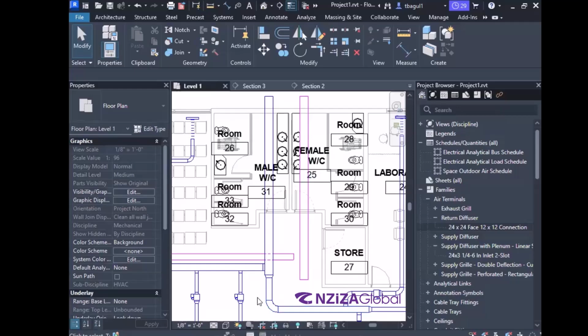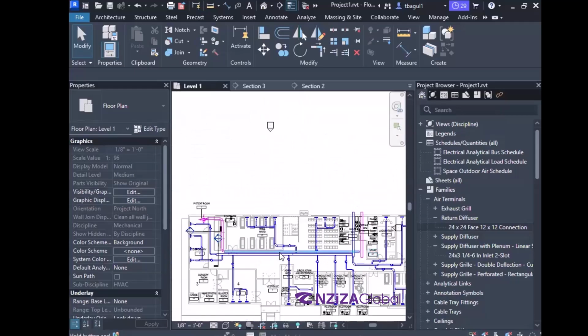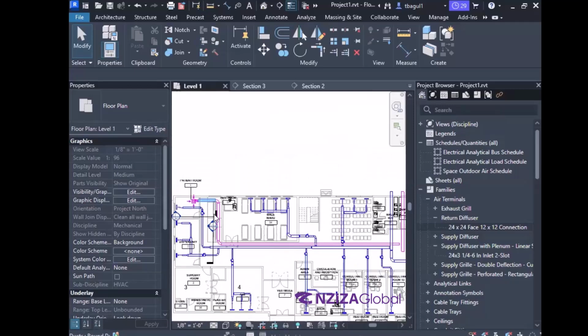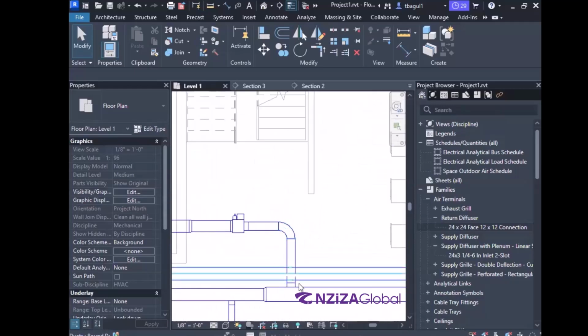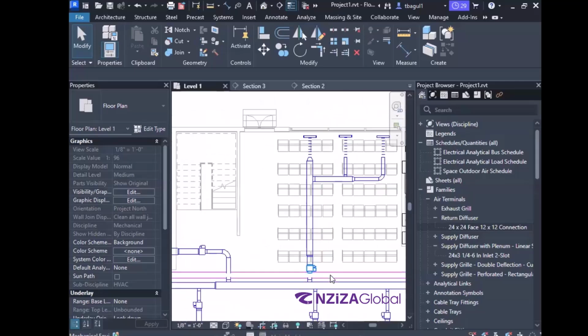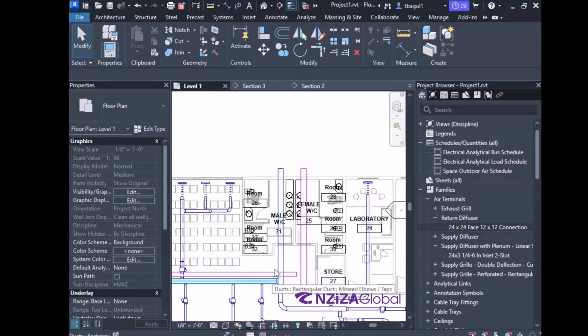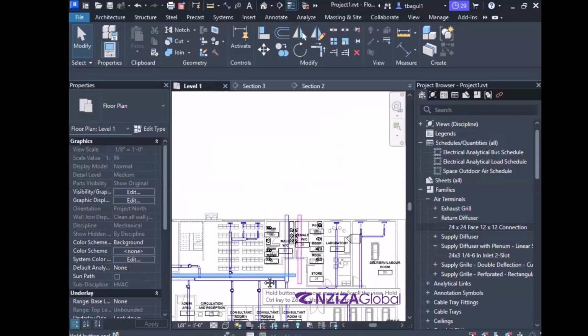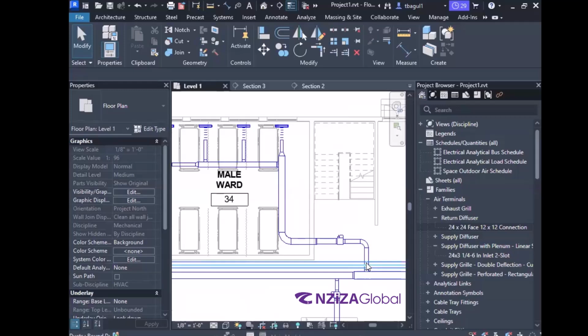Okay. So now that we have the duct, you see some points where the ducts are intersecting the return air duct, at least on the floor plan, right? We began from this point, we started drawing from here, but we see that there is some overlap over here, over here, and over here. Does that make sense? Your ducts might be oriented a bit differently since you tried to do it as practice, but try to identify the areas where the ducts are overlapping each other.